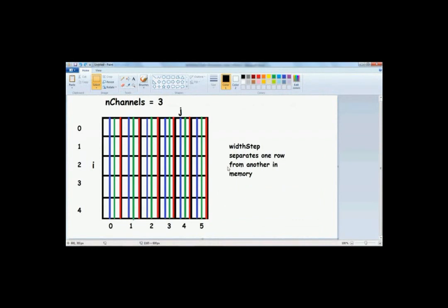We had mentioned before how the image is to be assumed as a 2D array of pixels. However, in memory, truly speaking, there is nothing actually as two-dimensional storage. It's all one-dimensional, it's all linear. One is stored after the other. So if you follow the cursor over here, once we go through here and we go to the last of this column, in memory the next contiguous location is actually the start of the next row. So that's how it's linearly related.